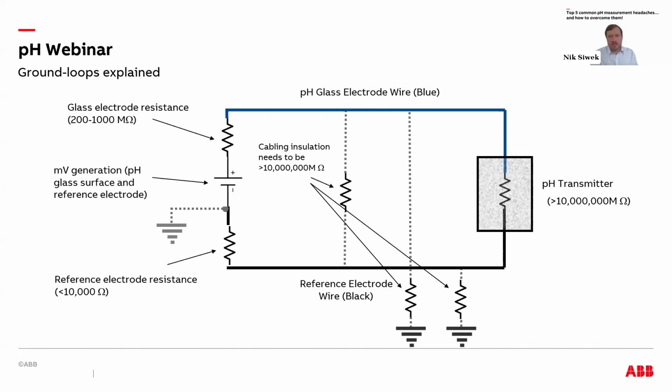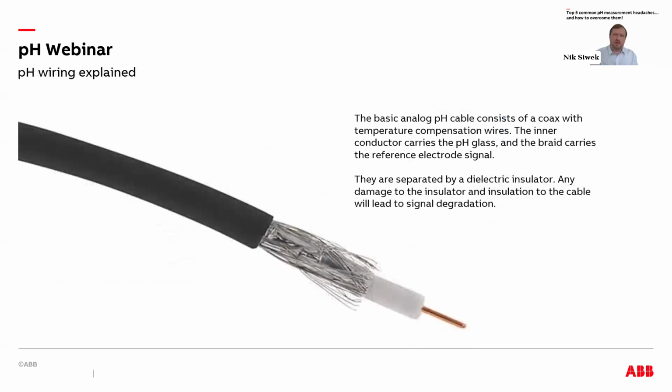If it is reading stable, I typically take a cable that's grounded to something and put it into the buffer solution. If the sensor behaves erratically, I know then that there's a grounding issue. So I usually look at the cabling of the sensor. That's typically one point to look at. If the cable's been modified, cut, bent, damaged, or nicked, that usually can lead to a grounding issue.